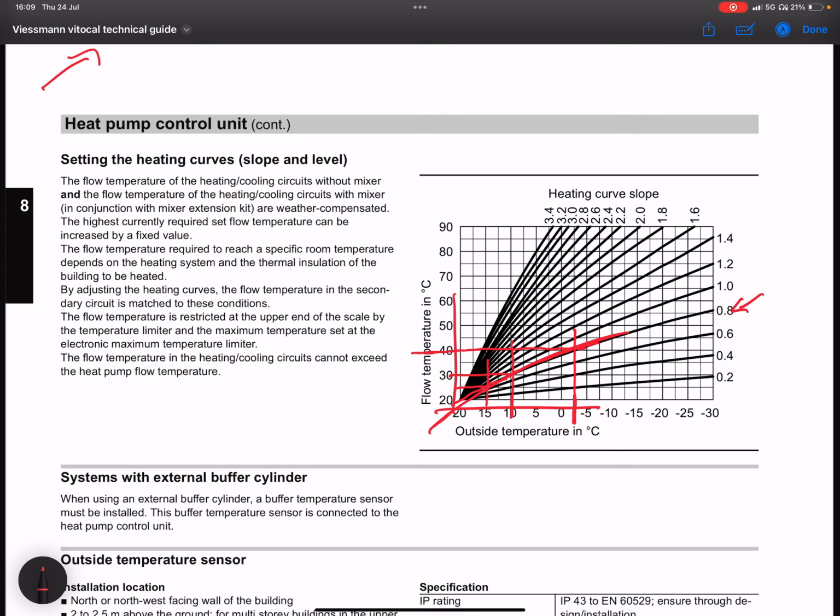And the reason that's important is because when you send an on-off signal to a heat pump, when they first start up, they are not at that 400 to 500% efficiency. They take a little bit of time to warm up to it. So you want your heat pump to be turning on and off as little as possible. The longer we can keep it ticking over at a very gentle level, the more efficient it will become. So running your heat pump off of a room thermostat that sends a signal to the heat pump is a very, very inefficient way to run your heat pump. So we install all of our heat pumps and boiler systems these days based off this weather compensation control strategy.